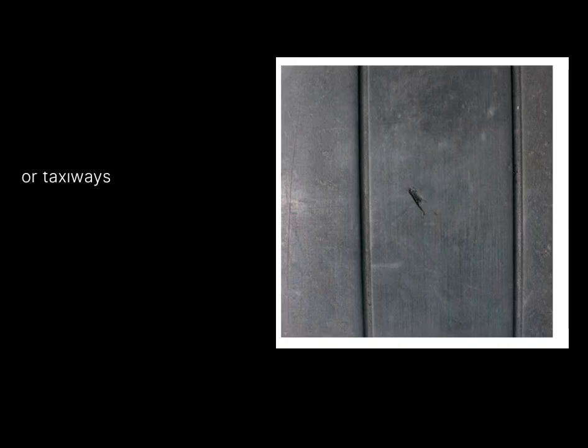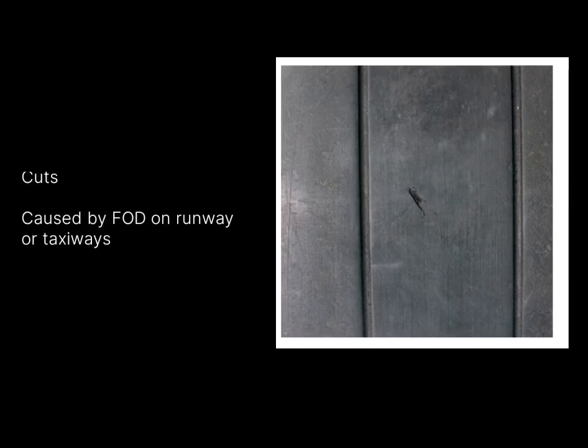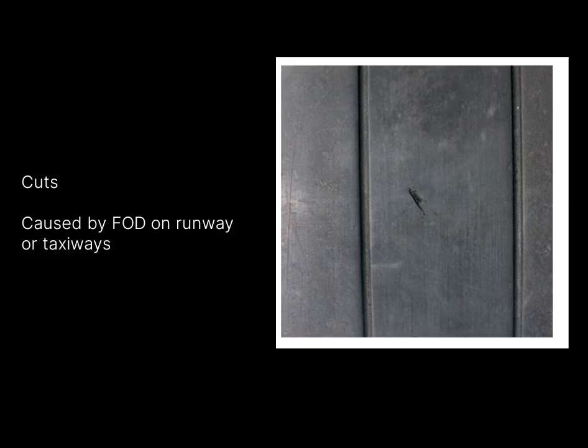Another type you can see is a cut on the tire, and there can be a number of cuts depending on the scenario. This is basically caused by foreign objects present on the runway or taxiway. If the cut reaches the carcass ply or belt cut limit, then the tire must be removed from the aircraft, and there is some length and width limitation also before releasing the aircraft.